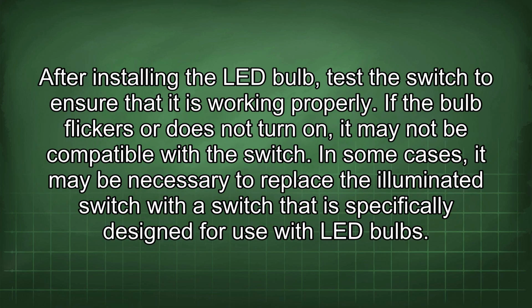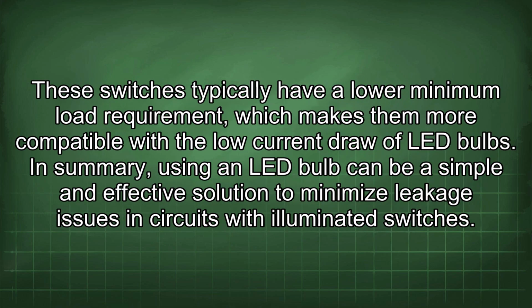After installing the LED bulb, test the switch to ensure that it is working properly. If the bulb flickers or does not turn on, it may not be compatible with the switch. In some cases, it may be necessary to replace the illuminated switch with a switch that is specifically designed for use with LED bulbs. These switches typically have a low minimum load requirement, which makes them more compatible with the low current draw of LED bulbs.